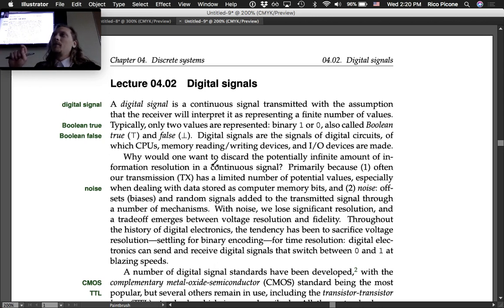You're going to have some voltage fluctuation if it's at non-zero temperature, just from what they call thermal noise. There are other noise processes too, and so sometimes noise will come in from some background electromagnetic field. So you could be close to something that's transmitting and your circuit might pick that up. You could be getting electrical signals coming in through electronic ways to your circuit, like especially it comes through power supplies a lot of times. You're powering your circuit somehow. That usually eventually comes from a source that is the AC line, and there's all kinds of noise in that.